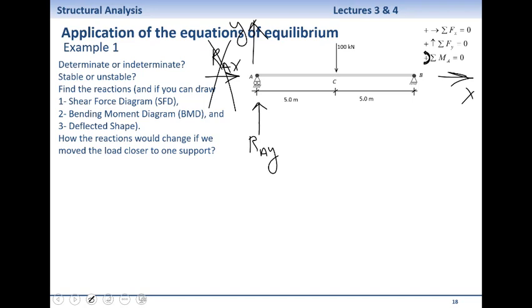That's the nature of a roller, that it can move horizontally. In this case, we can have a roller in the vertical direction, but in this case, it cannot. It can move actually in horizontal. So therefore, there is no resistance. What about point B? Can it produce a vertical reaction? Yes? Okay. Will that go upward or downward? We don't know really, do we? I know that it can produce a vertical reaction. I'm not 100% sure. I assume this is RBY.